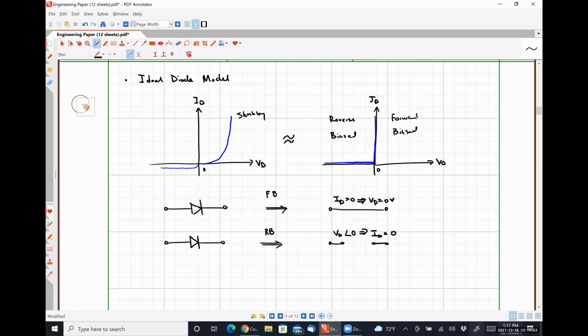Okay. So let's look at that same problem again, and I'm going to intentionally assume that the diode is off as my first state to show you guys how you interpret the results. If it's forward biased, so if we are assuming that the current flowing through the diode is positive, we say that there's no voltage drop across the diode. We don't have an estimation or anything. We're just saying it's 0. All of the current is passing through because this guy happens to be forward biased, or none of the current is passing through because this guy happens to be reverse biased.